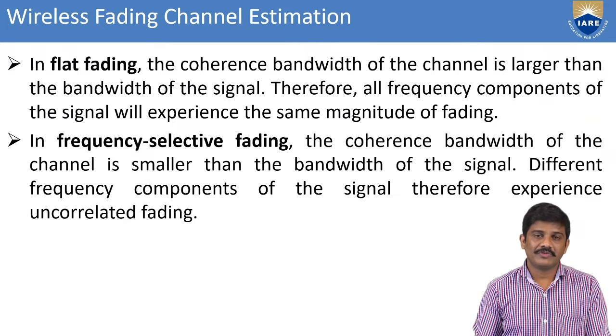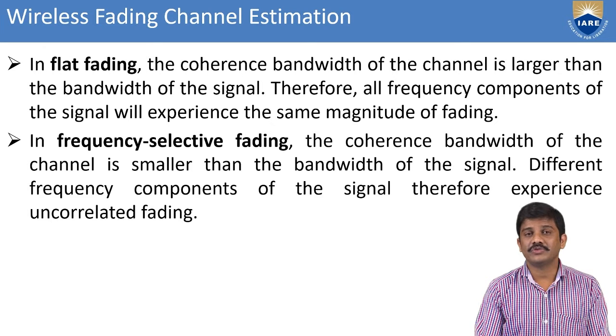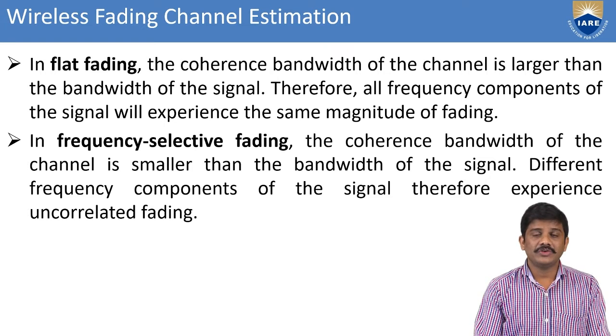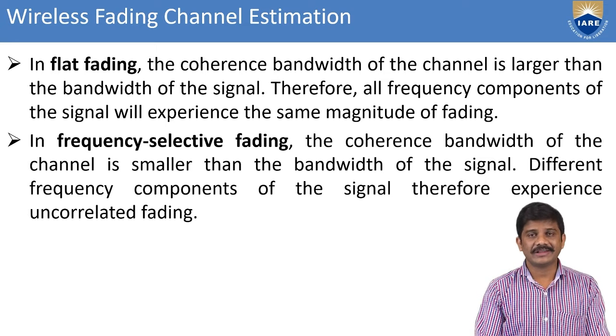Then you can go with flat fading and also frequency selective fading. Coming to flat fading, we have to take the coherence bandwidth of the channel, which is larger than the bandwidth of the signal. Then all the frequency components of the signal will experience the same magnitude of fading.